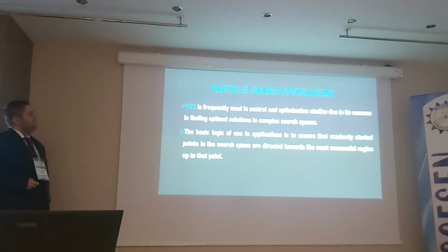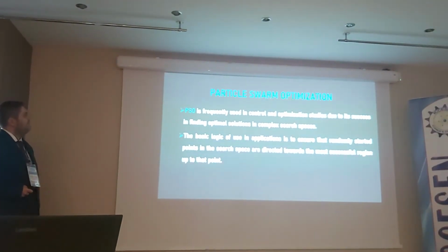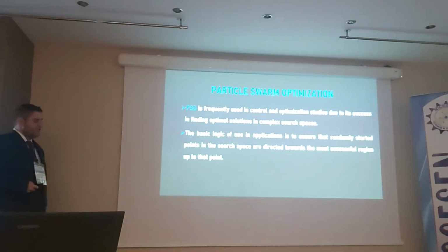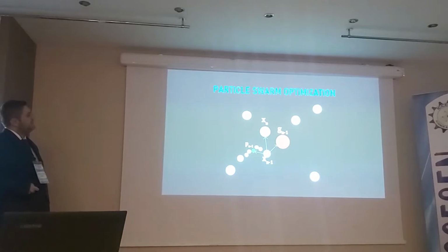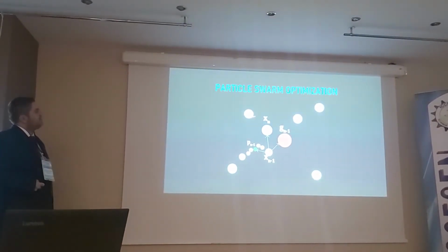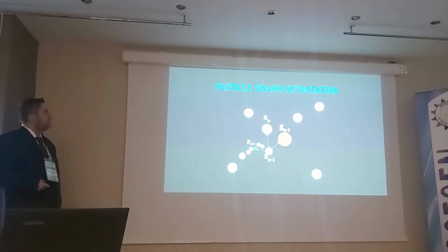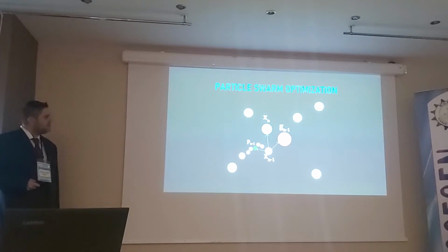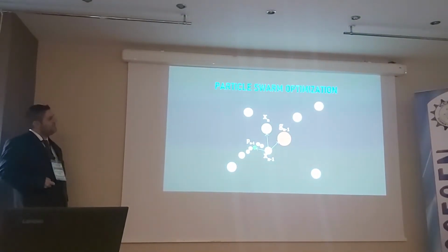We have used it in our other studies also, and we have shown that it is a very efficient and effective method. Graphically, we have several particles which are the Kp, Ki, and Kd parameters of the controller. Here we are using 2 dimensions, but actually it's 3-dimensional since we have 3 parameters.